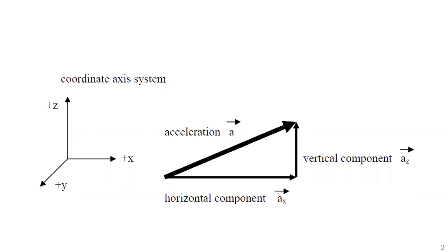Sometimes in groundwater flow, when we're looking at fractured rock, the X, Y, and Z directions, we actually align with the rock fractures. And they may not have 90 degrees between them. But again, it just helps us with the flow domain compared to where the rock is, the no flow domain. So typically when you assign the coordinate axis system and look at a little differential cube like we will, ultimately that falls out of the derivation.